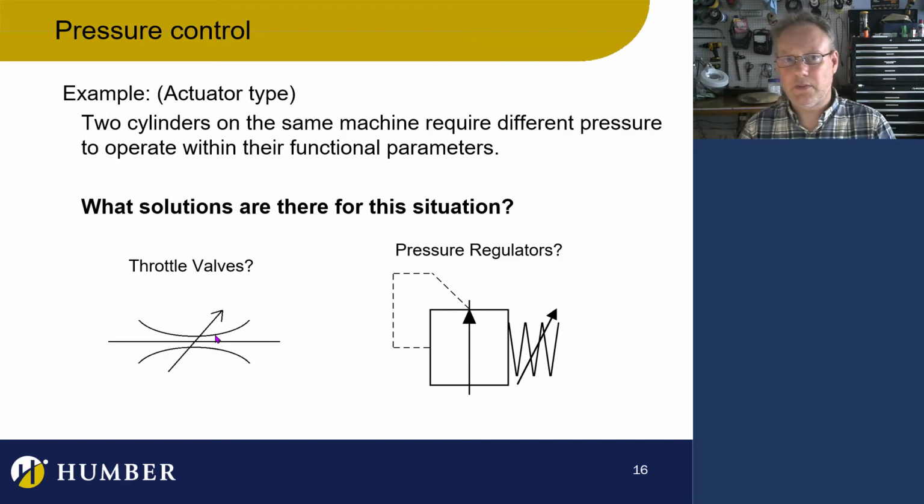There are two other ways to control pressure. One is we actually get a pressure control valve, or pressure regulator, and it's designed to actually regulate. Now, we talked about that in ancillary equipment. I went in depth on that, so if you want to know how that thing works, go back to that. The other thing is that we can use a pressure relief valve, and we can control a set pressure.